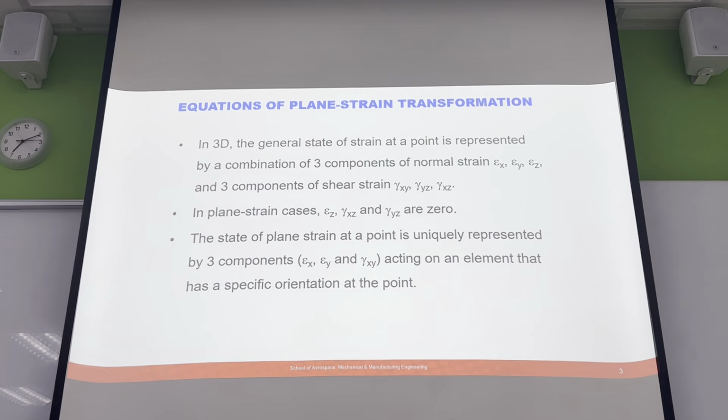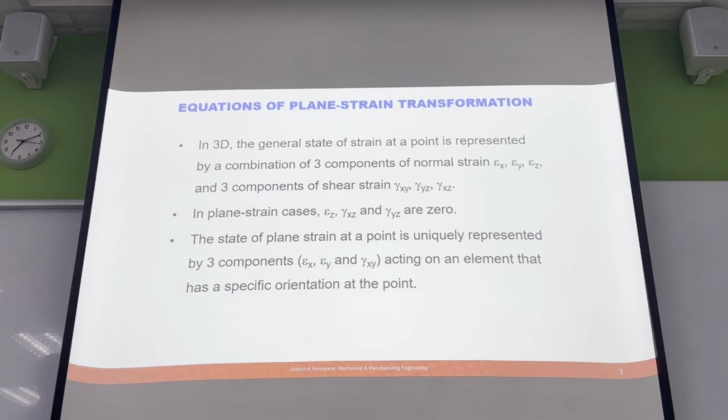If we know all those, then in any orientation we can figure out what all the values are, and then we can use those stress transformations to look at what the stress is in any other direction.